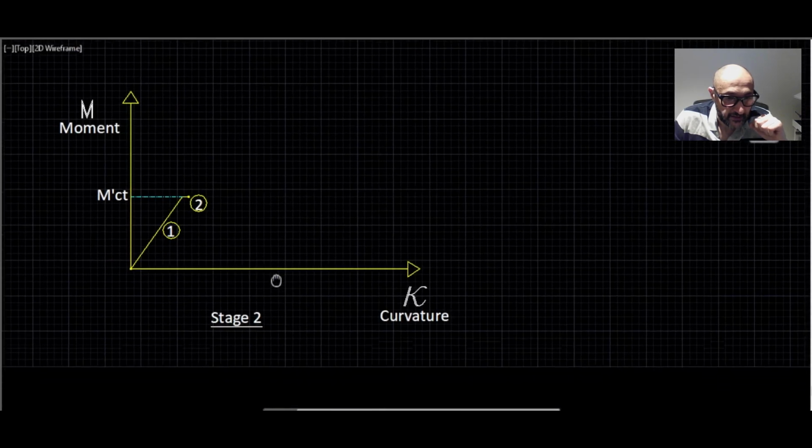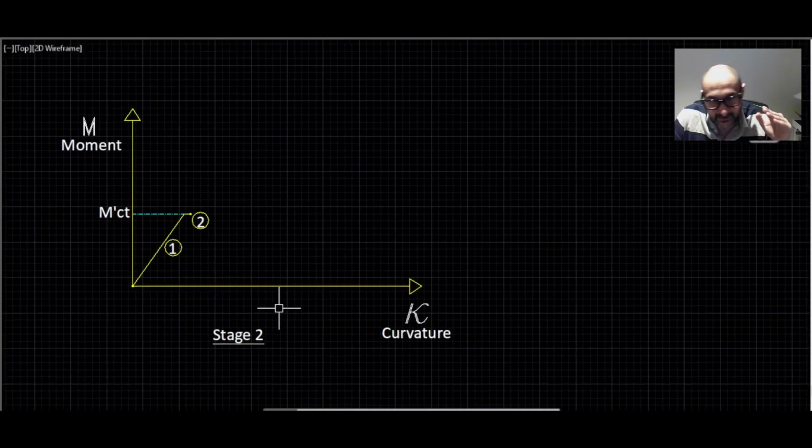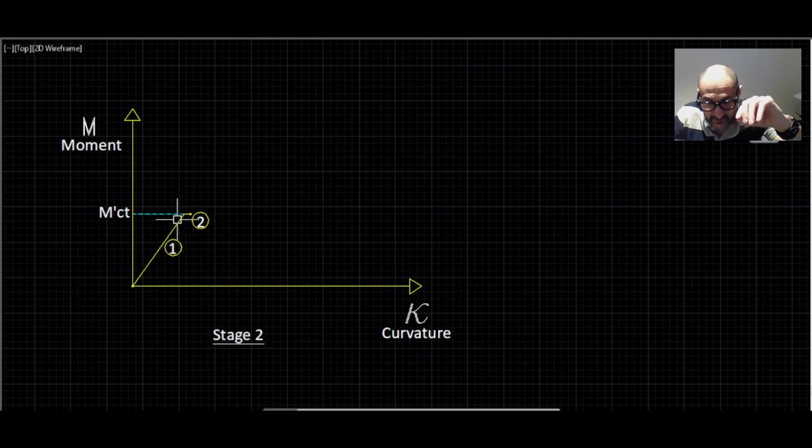All right, now stage two. As the load is increased, the concrete first cracks in the tensile region at the bottom here, because concrete is weak in tension and there is no reinforcement right at the bottom. There's no reinforcements, obviously, so concrete will automatically crack. And so the crack will start right at the bottom there, at that face, and the crack will propagate to the reinforcement bars.